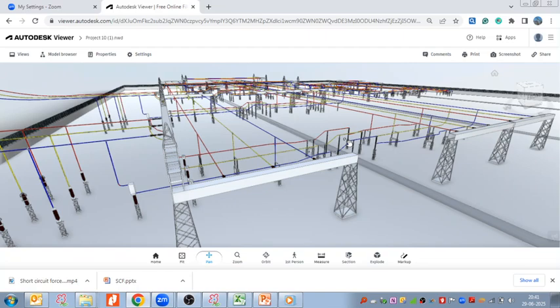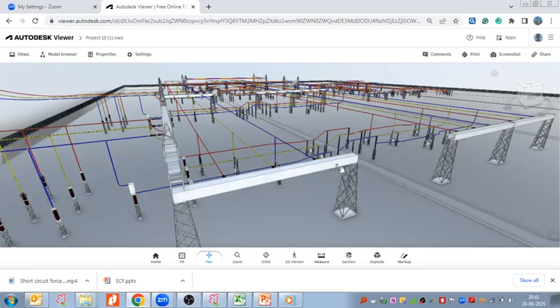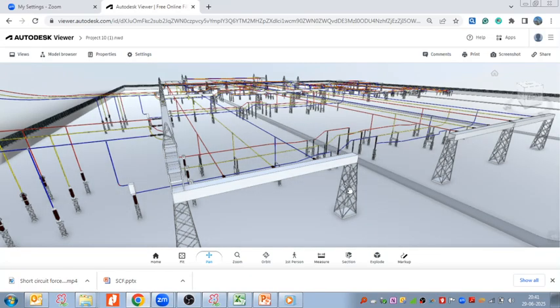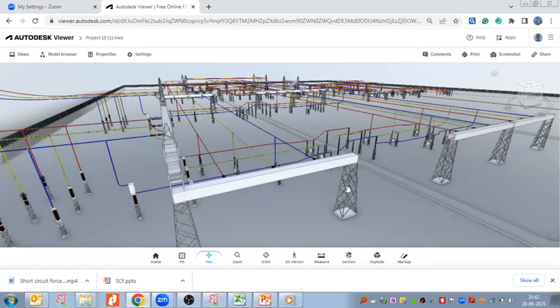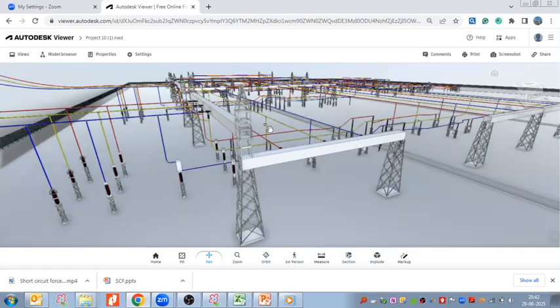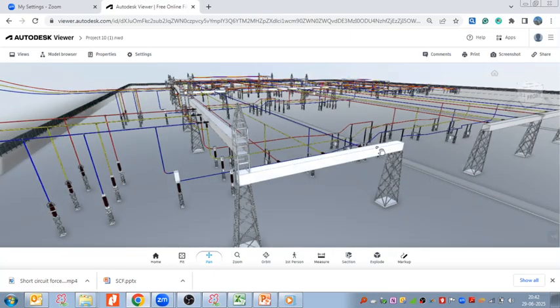For example, they will take the zone of the site where we are installing, and the wind speed, and based on the wind speed they will calculate the wind force coming on this structure, and the electrical short circuit force coming on the structure.